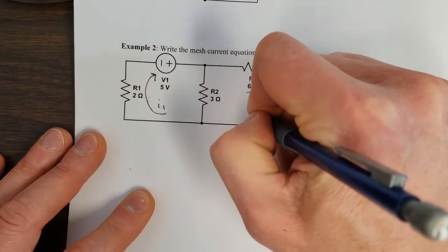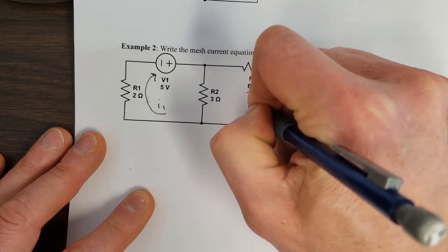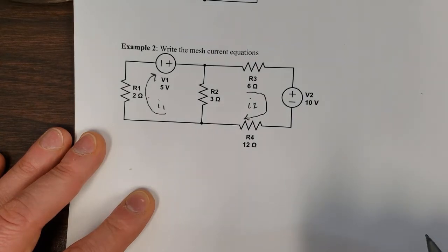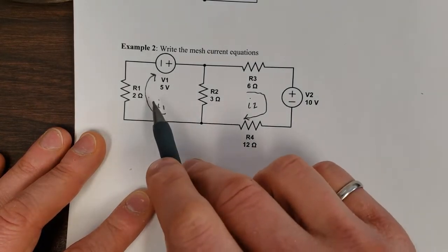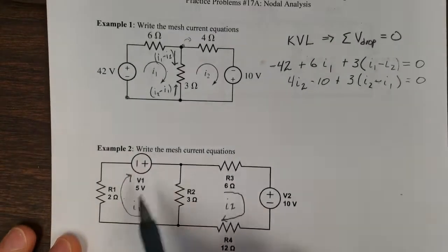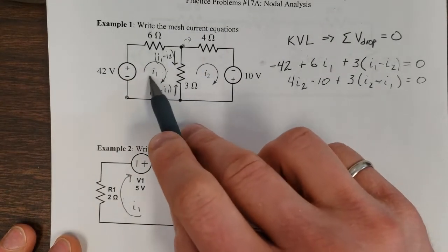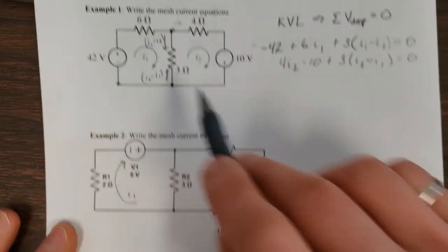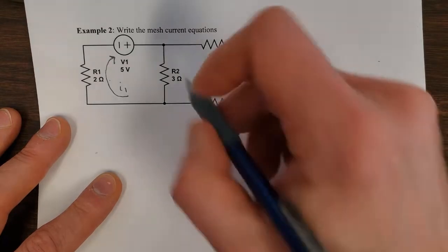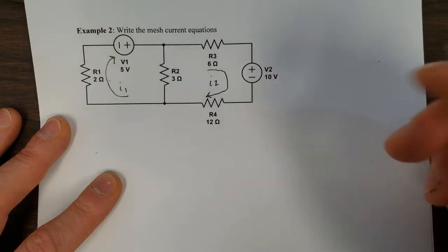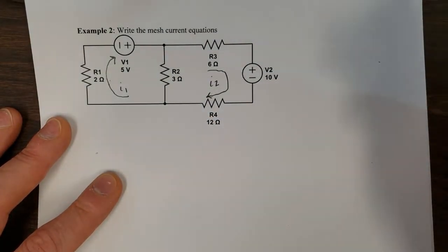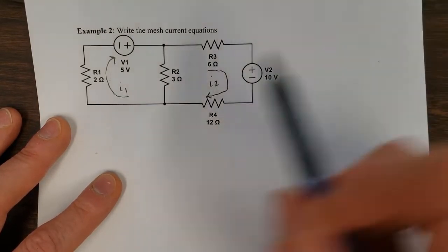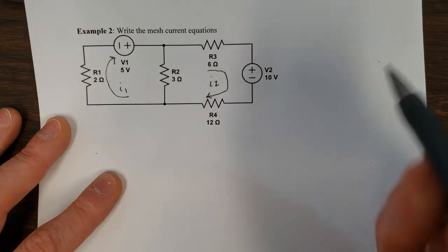Likewise, I2 is only the current that's going around this outside unshared portion. So make sure to keep that in your mind. The way they've drawn it up here makes it look like, oh, I1 is going through that 3 ohm resistor. No, I1 is only defined as the outside route for here too. Okay, we're going to have that difference in the middle term for the 3 ohm resistor when we do it. Well, we only have to write the equations. There's going to be 2 equations. There's going to be 3 terms and 4 terms in here.